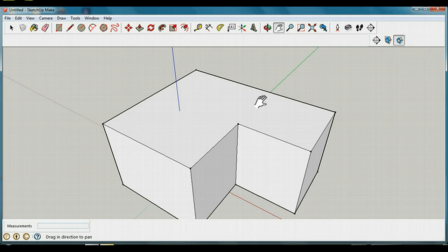Okay, now I'm going to raise this whole thing in a V-shaped roof, but I'm going to do it in a different way than I did it before. I'm going to use my pencil tool. I'm going to start to draw a line along the top of my roof. So I'm going to click on my pencil. I'm going to find the midpoint, which is the light blue dot. You'll notice if I move along here, it's red, but when I get here, I'm on exactly the midpoint.